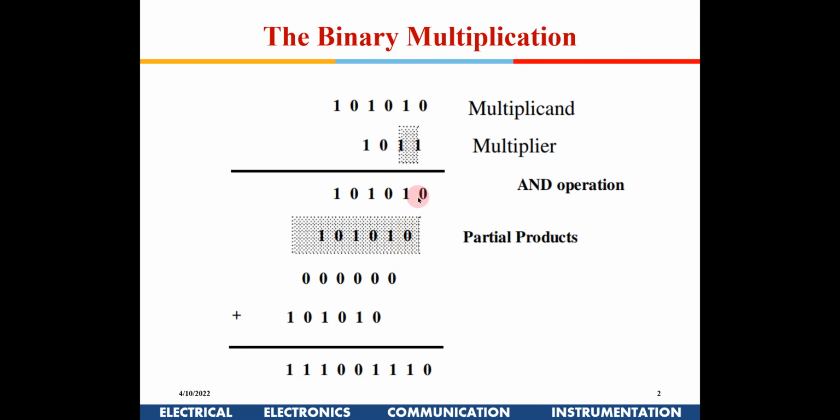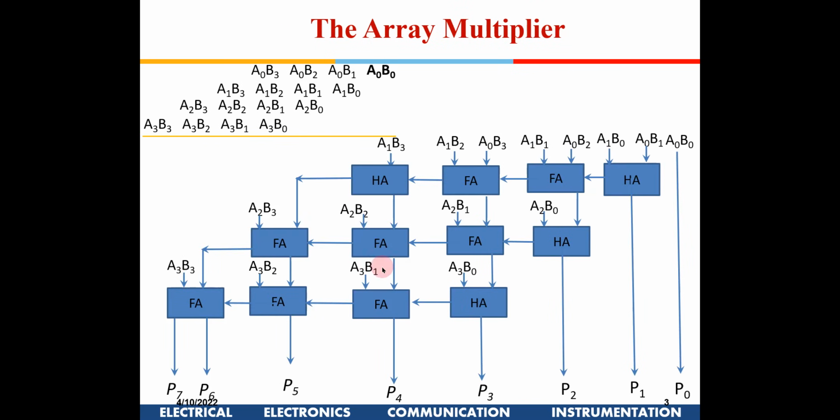And then, after the AND and the shift, the way it is arranged here, you need adders which could add all these things vertically. So these are the three things we need to do to implement it in hardware. There should be some arrangement where these things are shifted, and then you should have adders. Let's see how it can be done.